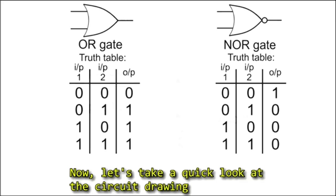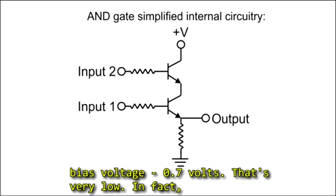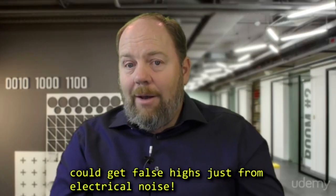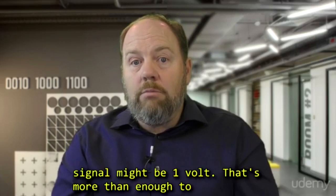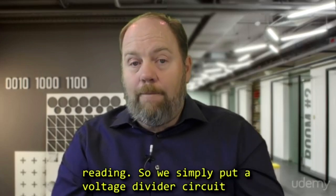Now let's take a quick look at the circuit drawing of the AND gate. We're using bipolar transistors, which, if you recall, have a very specific forward bias voltage, 0.7 volts. Now, it's very low. In fact, it's so low that depending on the circuitry, you could get false highs just from electrical noise. Now, if you have another logic gate further upstream, operating at 20 volts, for example, its low signal might be like 1 volt. That's more than enough to turn on the transistors, so you get a false high reading.